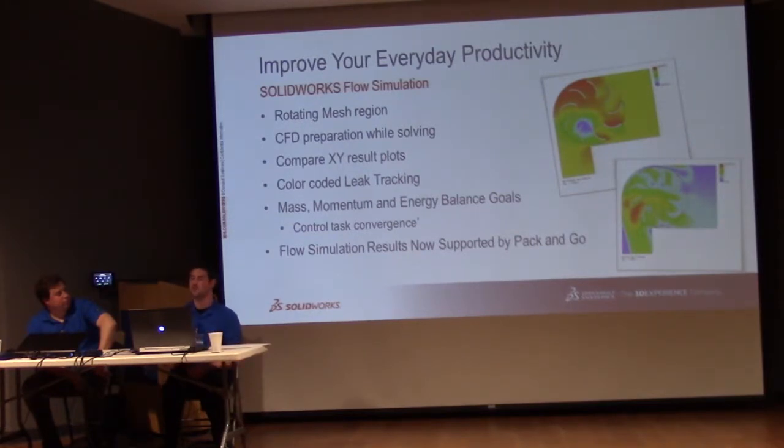We can also do CFD preparation while solving. So in the past, when we ran a flow simulation study, it would sort of disable our SolidWorks window, so we couldn't set up maybe our next study that we wanted to do. It sort of takes SolidWorks out of commission while solving on a computer. So oftentimes people would set up and run these overnight, or they would run them on a different computer after they did the setup.